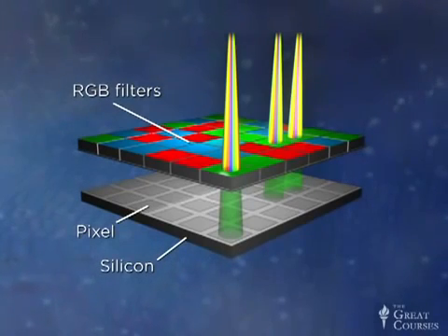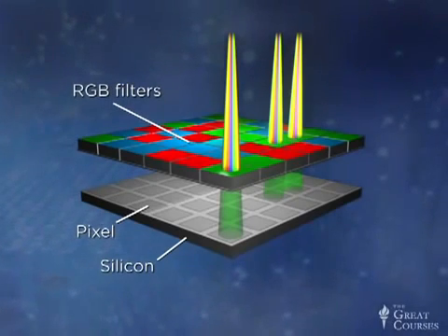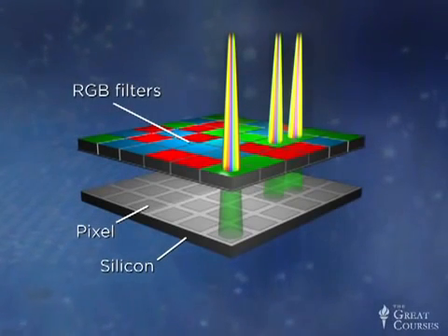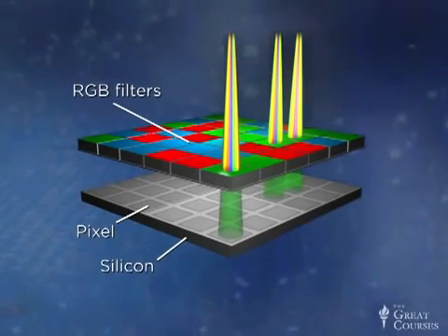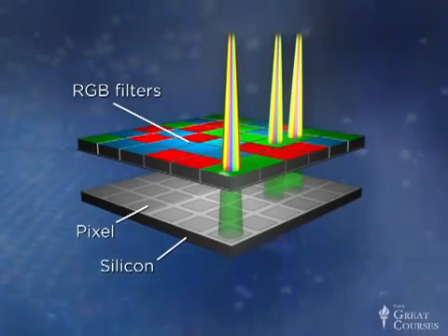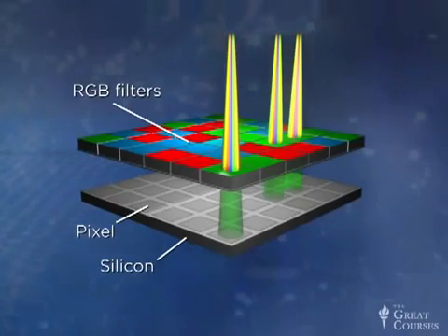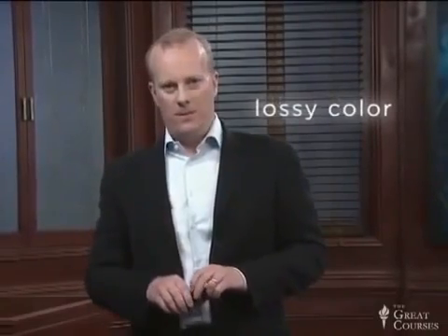When I say a filter, I really mean that we're only letting through our sieve certain photons, say just the green photons, and we're catching within our sieve the red and the blue ones. And so when we do that, we're further reducing the number of photons that end up impinging on each of the pixels within our image sensors. So this is what we call lossy color. It's an approach to seeing in color that does so by throwing away information.